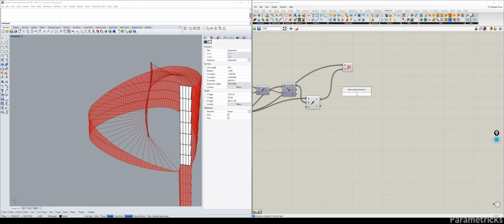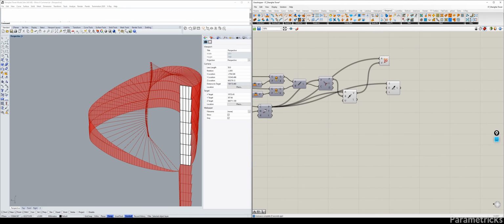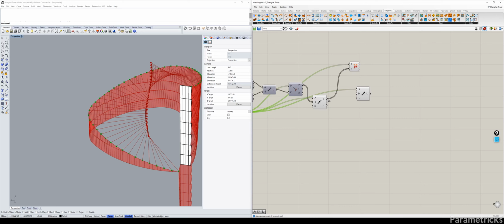The reason I want to do this is that I can use this vector to create my line by using an SDL command that comes from that point over there with the vectors as a direction, and then we can set a length for our lines. For example, let's start off with 1,000, with 1 meter, between 1 meter and 3, I would say. We can hide that.